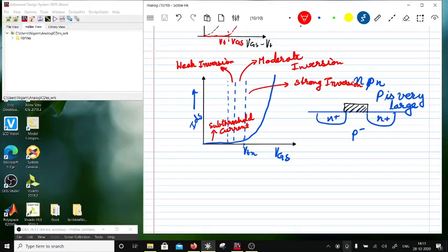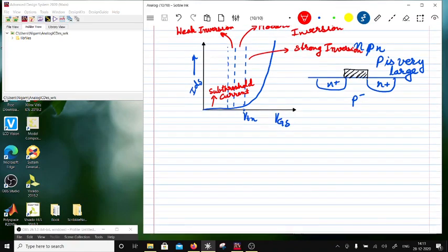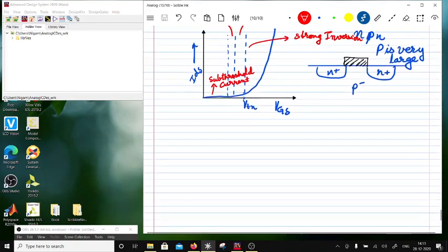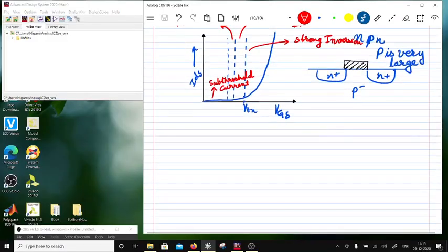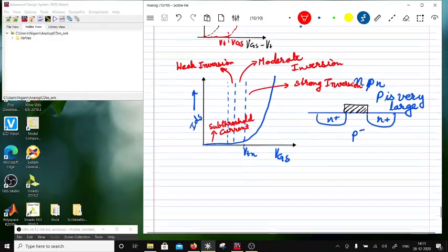So for example, noise consideration will be there, right? So you may take very large devices. You can make a low noise amplifier, operating the devices at very low current densities and very large devices. So usually that happens when you deal with medical or implantable circuits. So this is the transfer characteristics.